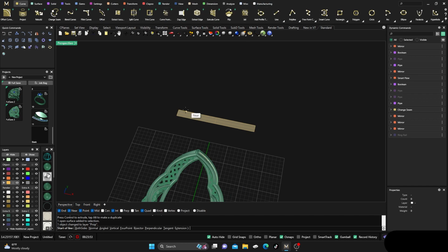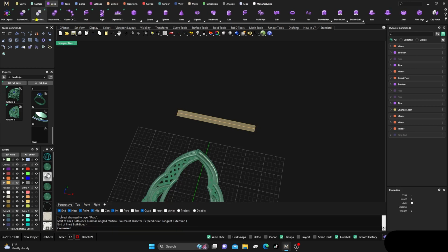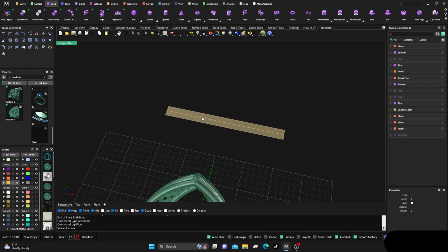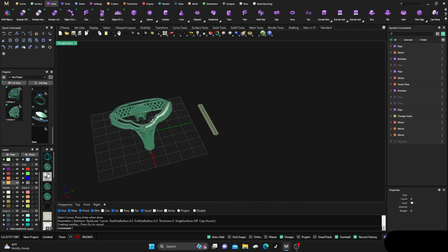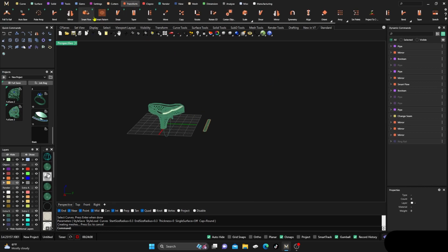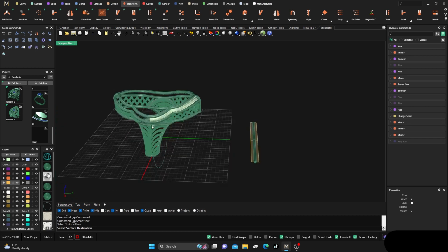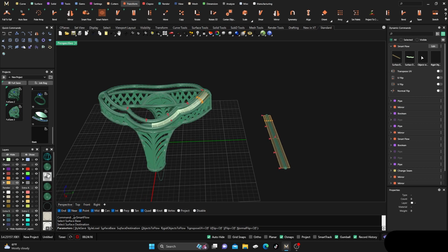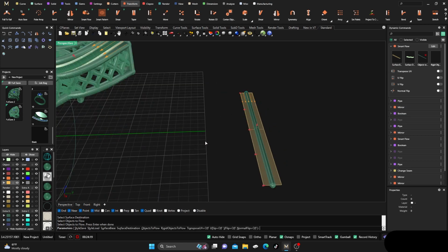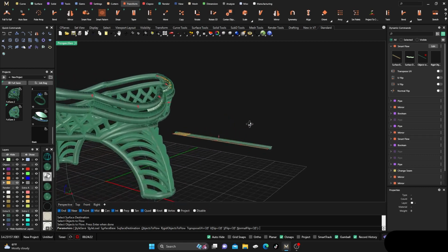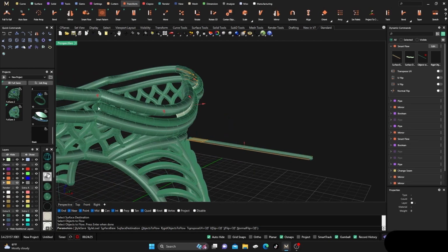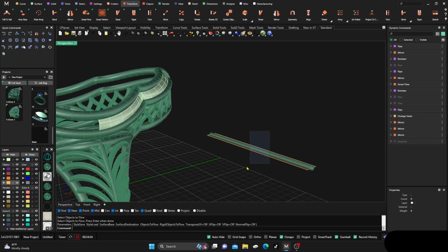To start with, let's just check it. So we'll get a line curve, snap to our mid, snap to our mid, and do that piping again just to make sure where our directions are at. Select our curve, enter, enter, and then let's do that smart flow again just to find out how much this is taking up. There, object, there, enter. Yeah, see, that's going all the way to that original part, remember, before we cut it off, that section there. So that's not what we want. So let's take all this and delete it.